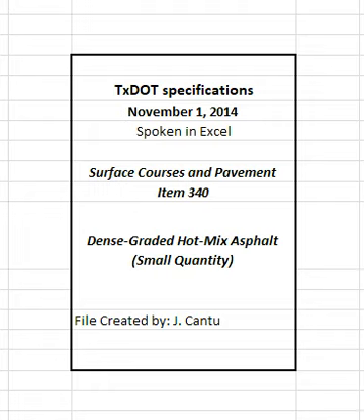4.6 Placement operations. Collect haul tickets from each load of mixture delivered to the project and provide the department's copy to the engineer approximately every hour, or as directed. Use a handheld thermal camera or infrared thermometer to measure and record the internal temperature of the mixture as discharged from the truck or material transfer device, MTD, before or as the mix enters the paver, and an approximate station number or GPS coordinates on each ticket unless otherwise directed.